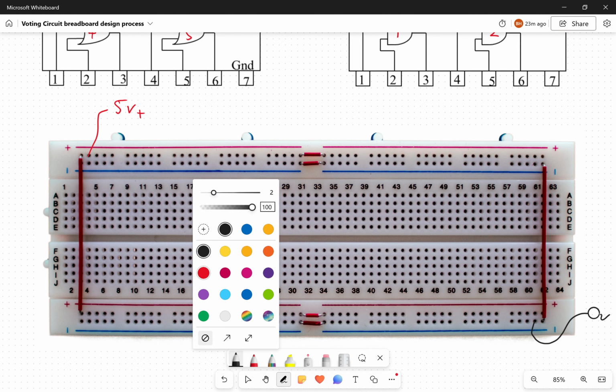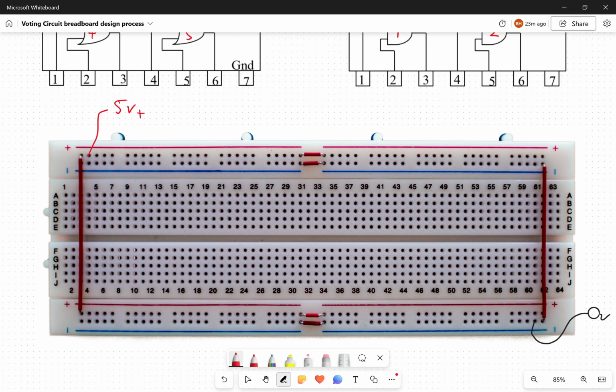So by putting these in, we're just doing the basics of getting the circuit ready to be built. Now when we build these, we'll be using a kind of dual inline switch block, which is like a dip switch, 4-way, I believe it is. 1, 2, 3, 4. So I'll take 4 dots. We're just going to roughly sketch that in there. Essentially what that will be is just a little switch block that will bridge the non-conductive gap in between the breadboard right there.